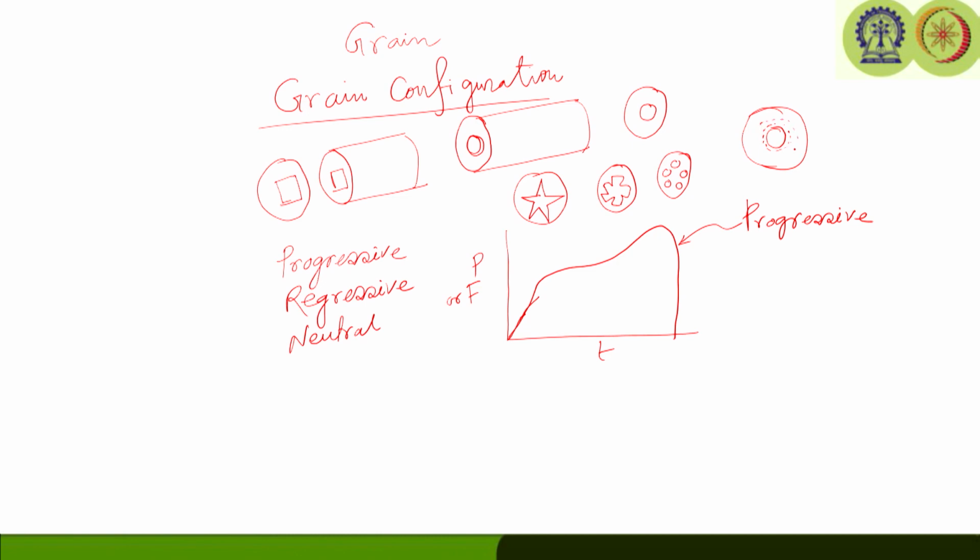It will keep on going as time proceeds, until it reaches the final diameter of the grain, or up to the internal liner of the motor casing. Okay. So, here we can see the burning surface. Let us say this is the initial burning surface area ABI, that will go up to the final burning surface area here, which is ABF. So, it keeps on increasing.